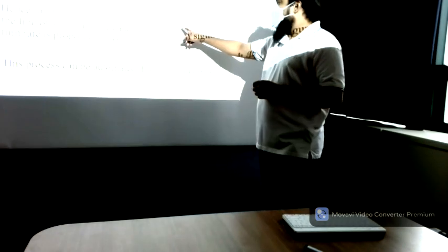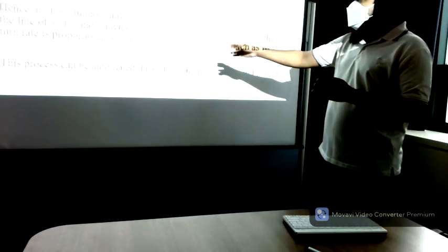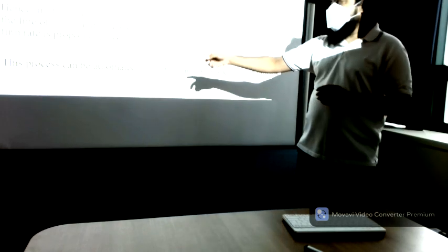Hence, in this situation, navigation consists of estimating the turn rate of the line of sight, and guidance consists of steering the missile so that its turn rate is proportional to the turn rate of the line of sight.